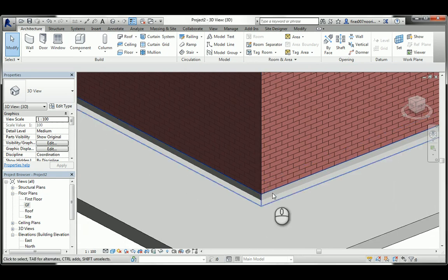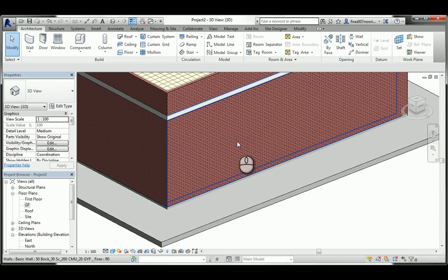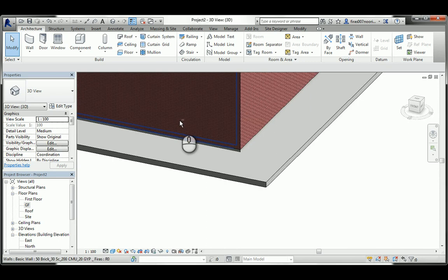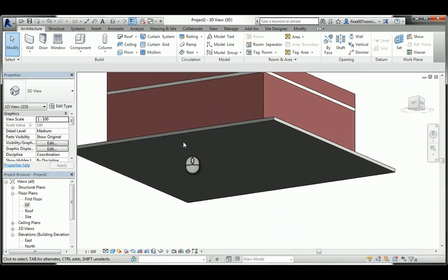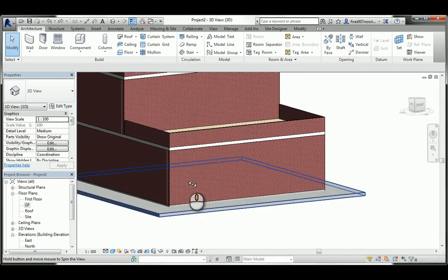When we finish this issue, I'm going to show you how the brick goes down. You're supposed to see the brick actually touching the walkway, which is the correct thing. But again, that's what I want for now. This is really important if you want to open the door here without any canopy, so the rain doesn't go inside. The outside walkway must have a lower level than whatever is inside. So if I look down, I will see that, hang on, the slab goes all the way under this. If I delete it, there's another slab. So 2 slabs, it isn't okay, it's not right.